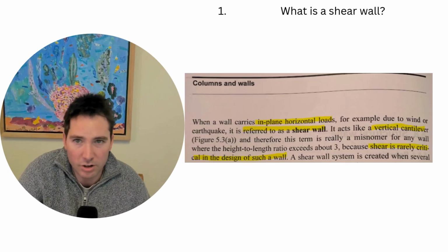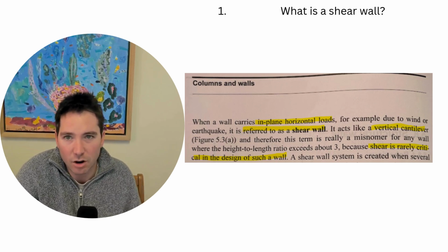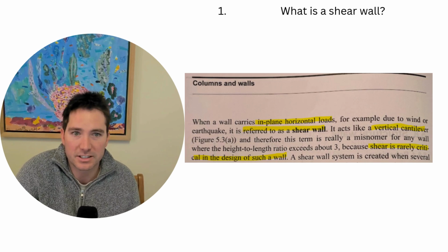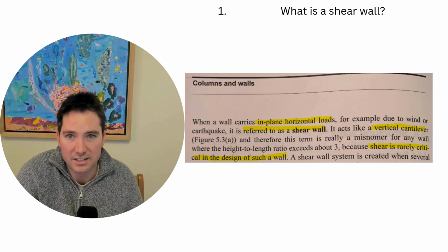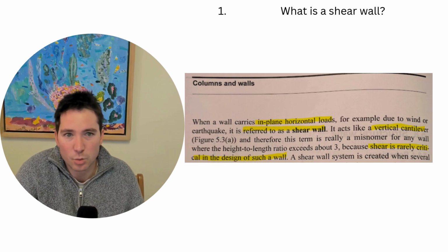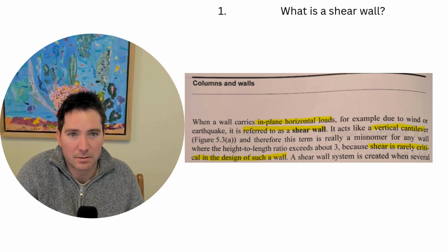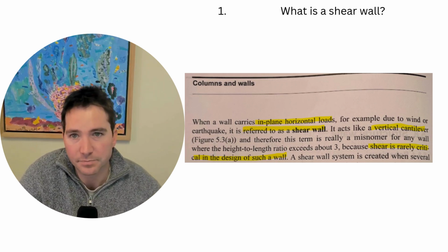It's somewhat of an ironic term, because usually shear walls essentially act as large cantilevers off the ground, and typically they're designed as flexural members, as you would with cantilever members. But they're not really governed by shear typically. Shear walls are the most common lateral stability system for buildings here in Australia.